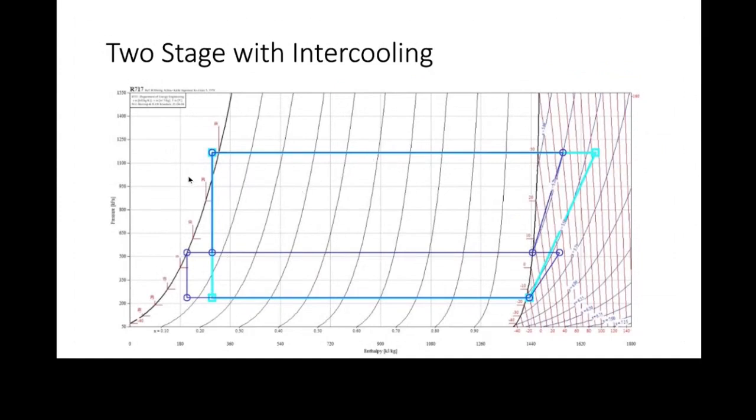And what I've done is taken the same thing under standard pressure and temperature conditions, okay, same as before. And the original one, we had plus 30 for the condenser, and we had minus 15 for the evaporator. And the original scenario was this light blue line where across the expansion valve we've got a big pressure drop that results in a lot of flash gas. In this case, it looks like about 15% flash gas and 85% liquid remaining.